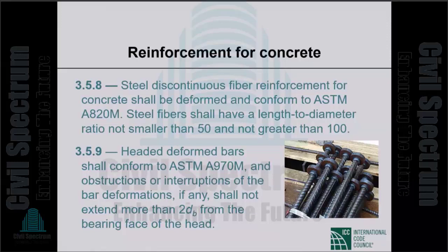Okay? Both ways, these are headed bars. The headed bars are becoming more and more common, and they definitely are recognized in ACI 318. With headed bars, the development length requirement goes down because stresses are transferred not only by bond between the bars and the concrete, but also by bearing of the heads. The bearing of the heads on the concrete transfers a part of the stress that needs to be transferred between the reinforcement and the concrete.